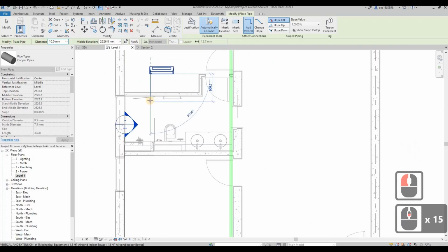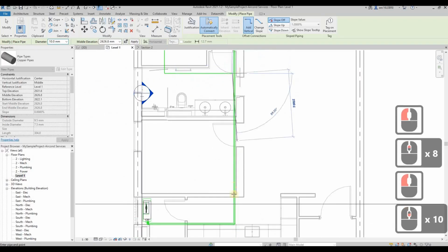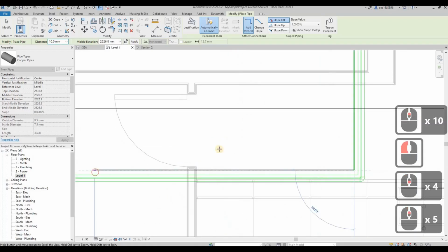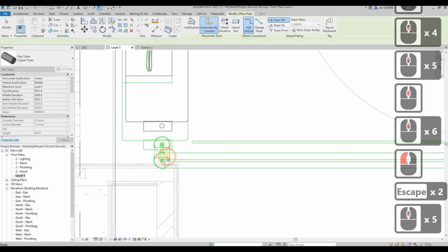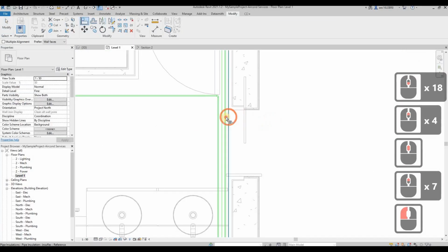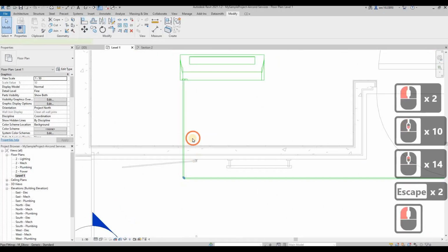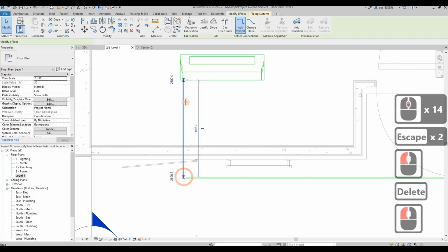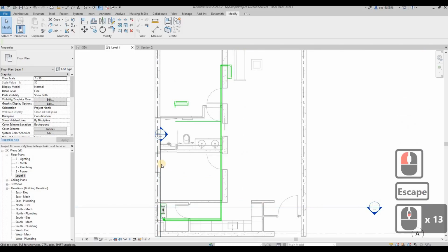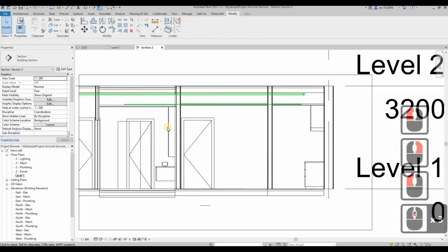Draw your pipe. And of course, logically, you will follow the same routing. You will bundle your pipe together. Then let it drop at the same point here. Of course, one up, one down. You can set it to one up and one down, so you can bundle your pipe together. And of course, you need to delete this because you know that you're going to adjust the height of the piping. Then from the section view here, you adjust your pipe height.